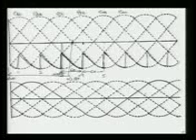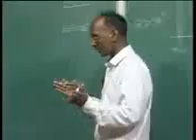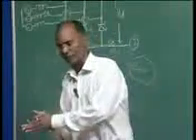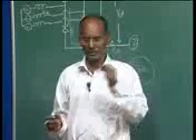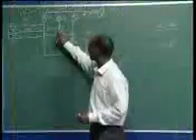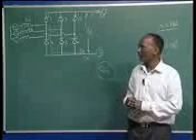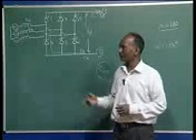Now the main important point here, although this is a very simple case where we are assuming the overlap angle is 0, means commutation from one valve to another valve is sudden and instantaneous, because when you are getting the pulse, 3 is taking complete current from here and the sudden switch is there. But it is not true, and we will see in the next cases when the various modes of operation will be there.